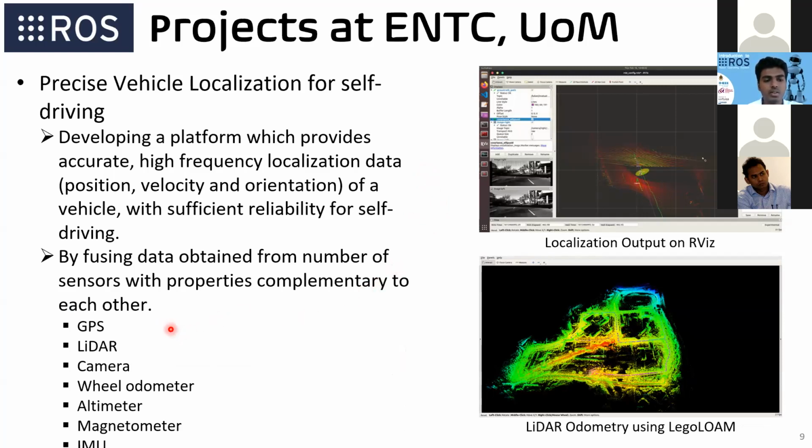It uses many different sensors like GPS, LiDAR, camera, IMU, odometer, and stuff. Those sensor data are then integrated through sensor fusion, and used by different algorithms to estimate its location.